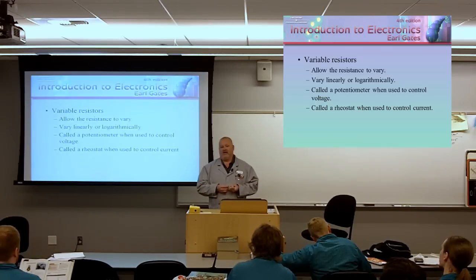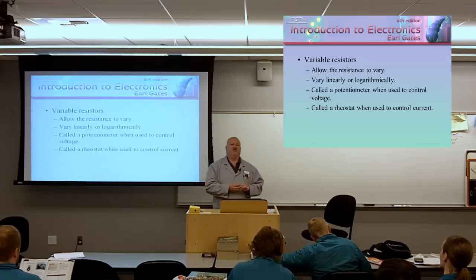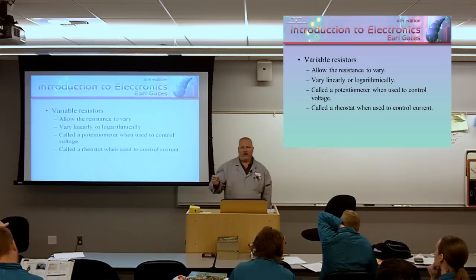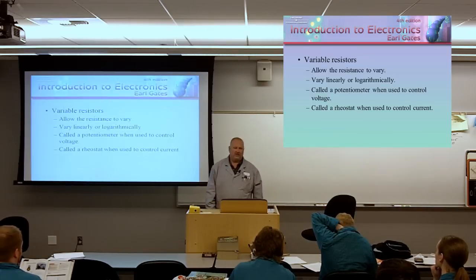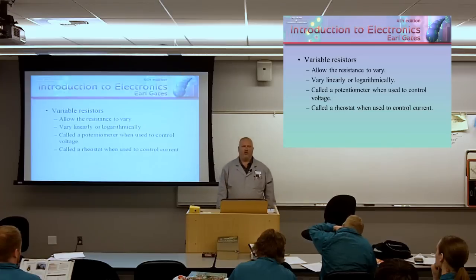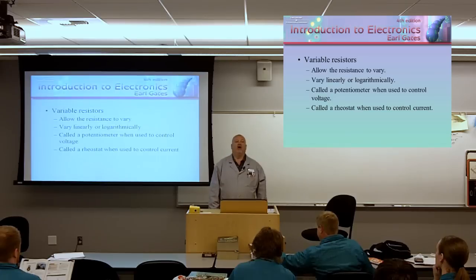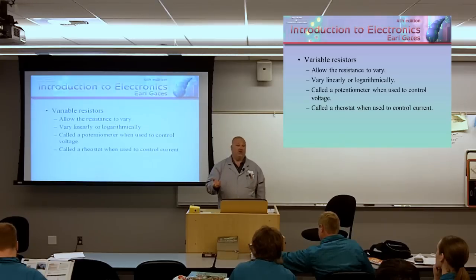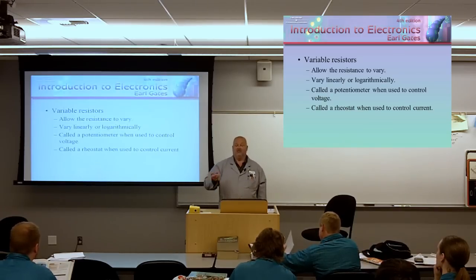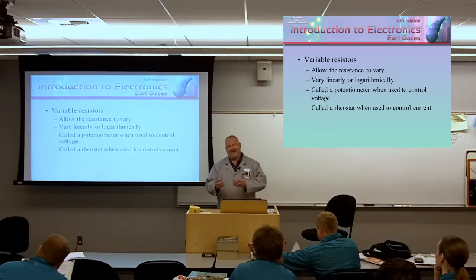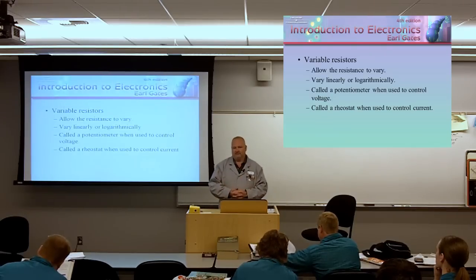If you're shopping for these variable resistors, you may also see it say audio on the box because it's for use with audio. So volume control on a radio, on a stereo, would be a logarithmic control because it's controlling something that is nonlinear. And what we're trying to do is get somewhat of a linear response out of it, right? When you turn the volume all the way up to 100%, you expect to get 100%. When you turn to 50%, you expect to get 50%. But since audio is nonlinear, we need to use a logarithmic control to get a linear type response. Make sense?